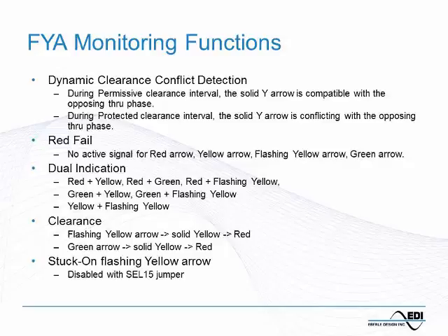There are also some controllers that don't have the capability to map the signals according to the way the compact mode expects them. In that case, they drive the flashing yellow arrow signals as the odd signal on 9, 10, 11, and 12. So if you are running that controller in that mode, you'll have to turn this function off because the monitor is expecting the flashing yellow arrow to be on 1, 3, 5, and 7, and instead it's going to find it on 9, 10, 11, and 12. So normally we don't have to mess with the jumper, but it's there in case we do.